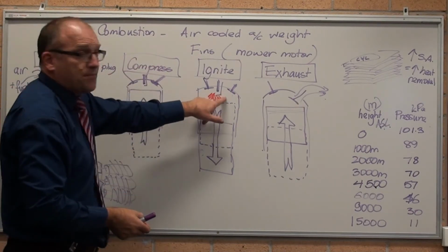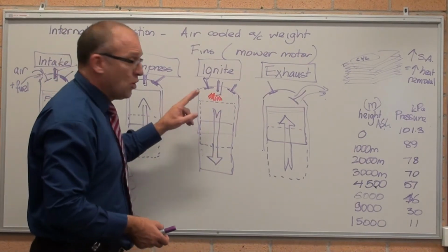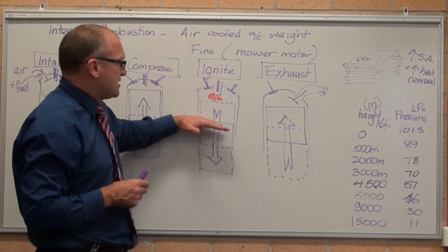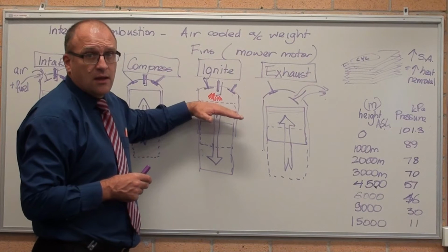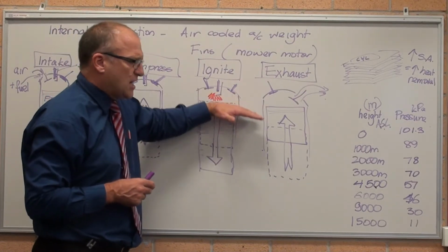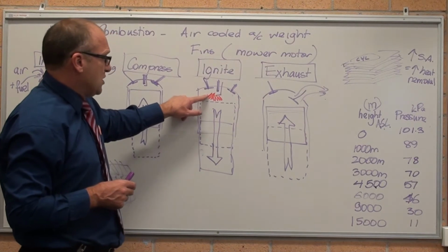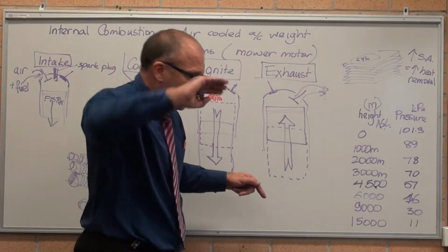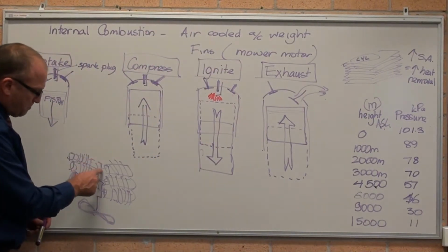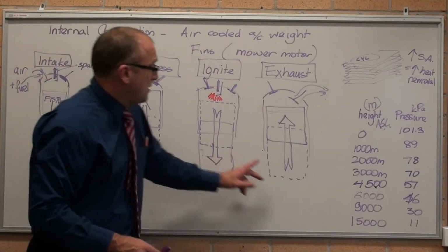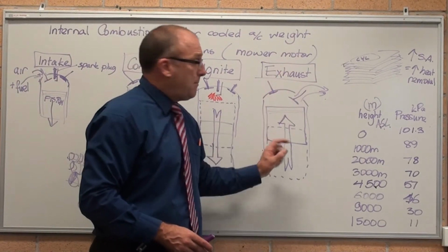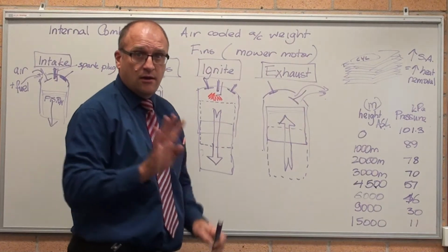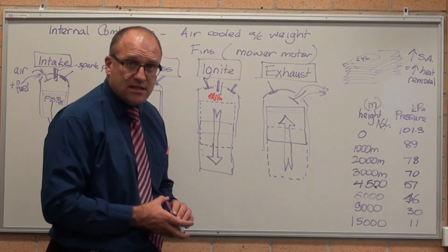increased temperature. Third step, the spark plug ignites the gas, or a fuel injector injects fuel and ignites it. Usually that happens just as the piston's getting to the top, and then by the time the fuel ignites, the piston's just starting to move down. So ignition is the third phase, drives the piston down rapidly. That's where you get your power from. The momentum carries the crankshaft round. The crankshaft's this purple thing I've drawn in the middle. It pumps this piston back up while the exhaust valve's open and the exhaust gas disappears. That's the basic operation of an internal combustion engine.